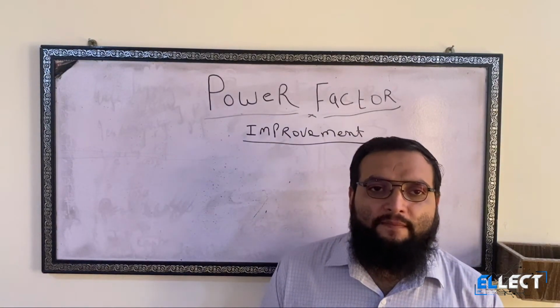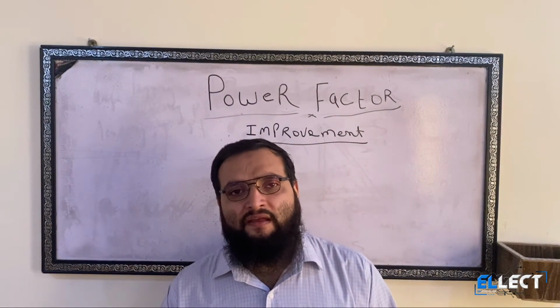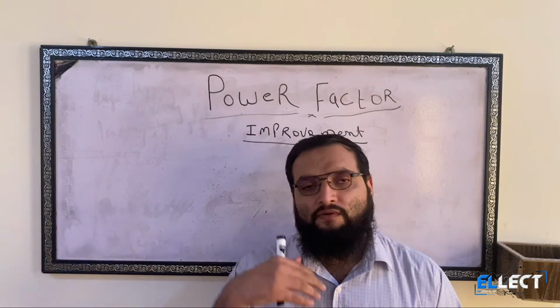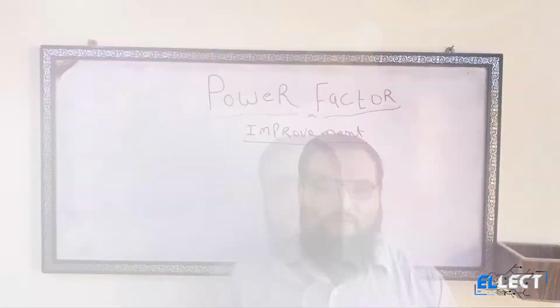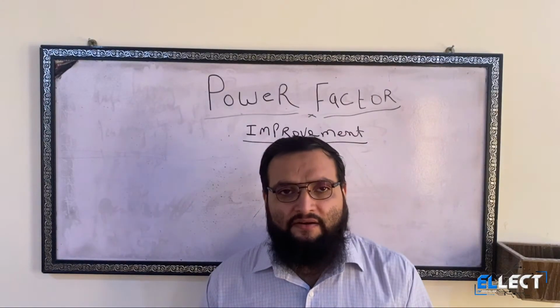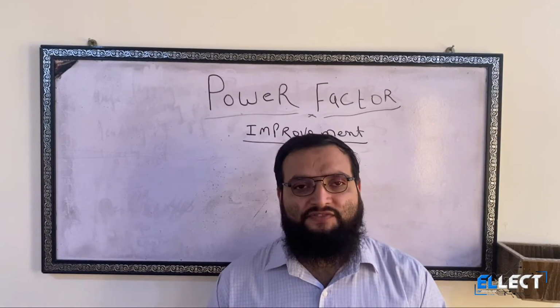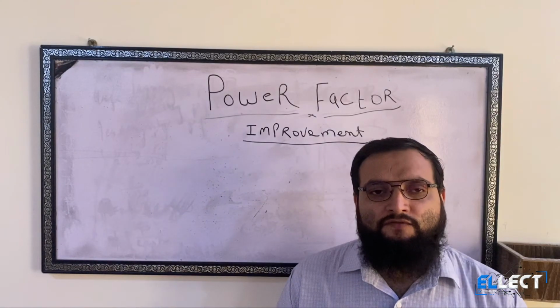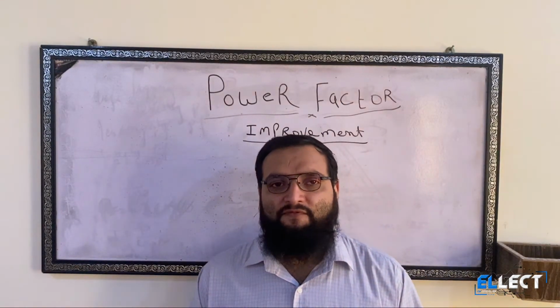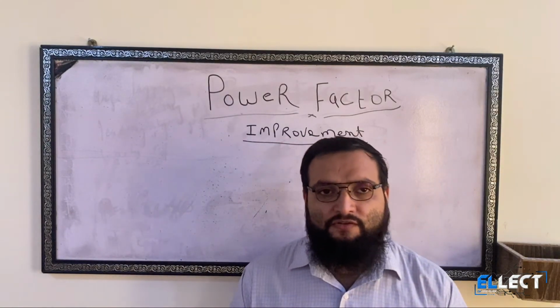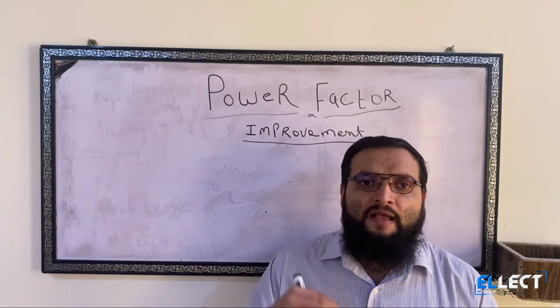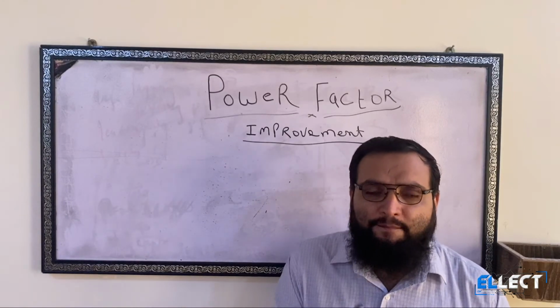If we increase the exciting ampere turns by an external AC source, it does not affect the current going through the stator winding. That is why this process is called phase advancer. So the phase advancer process is generally used to increase the power factor by exciting the ampere turns of the motor.